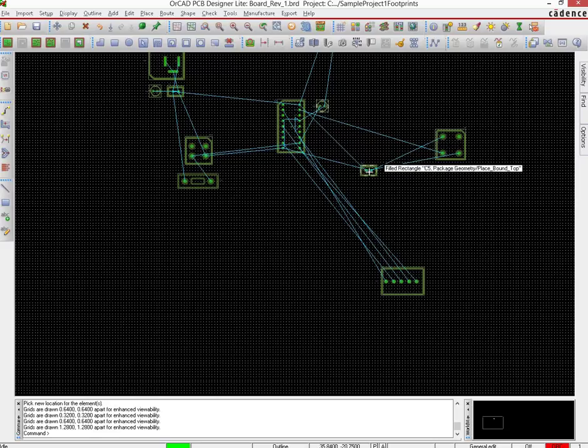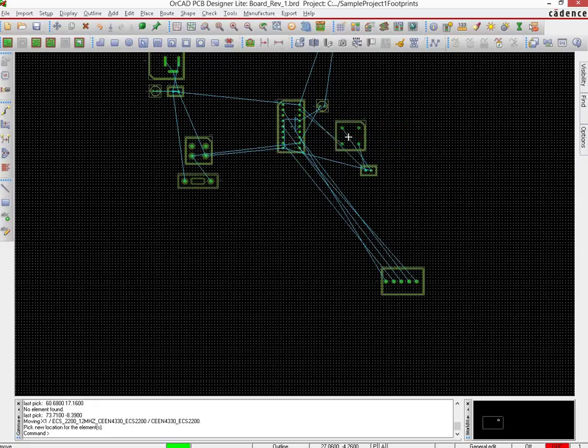Then the other thing that we need to do is we need to have the clock. Okay, now where does the clock go to? The clock goes to the microcontroller, the micro or the clock IC. So let us place it again close to the IC, as close as we possibly can. And then the other thing that is related with it is this C here. So that is something else that we have placed.